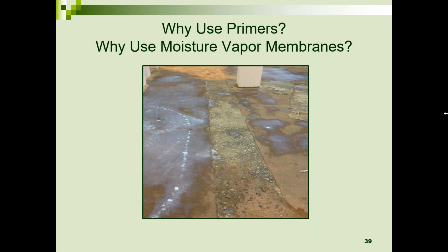Another area of concern: you've got an existing concrete slab, it's been trenched for whatever reason. And look, they've applied primer, but it's been absorbed almost completely on that trench surface. So the contractor needs to go back and reprime it. Generally on very, very porous substrates, read the manufacturer's tech data sheet for primers, but typically you dilute with water the first application so it can readily soak in, and then you apply a second application full strength to handle this very porous substrate.